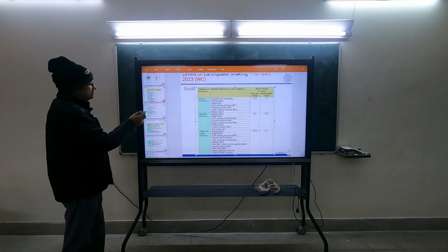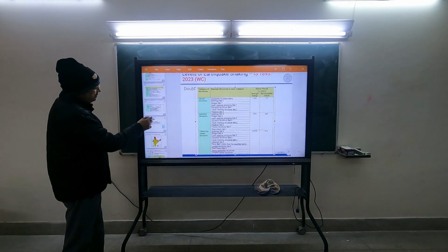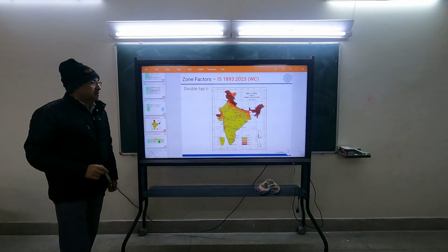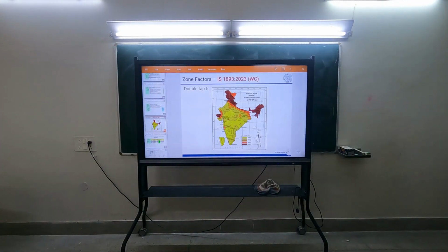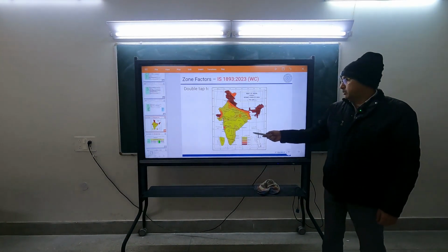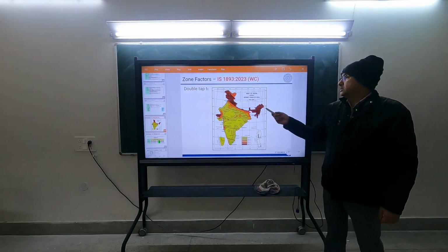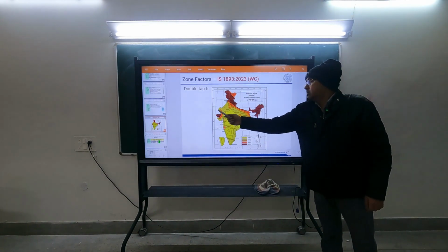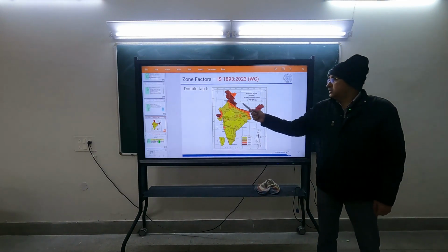Not the factor. And if you look at these values, this is the new zoning of the country. Currently, how many zones are there? 4. Now 5 zones are proposed, starting from zone 2, but a zone 6 has also been introduced here. So this is zone 6, central Himalayan region and Bhuj, Kutch area of Gujarat. This is in zone 6.